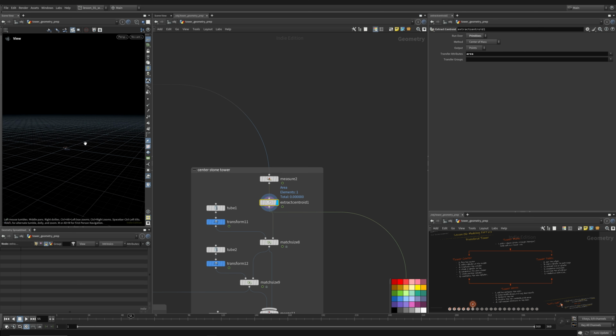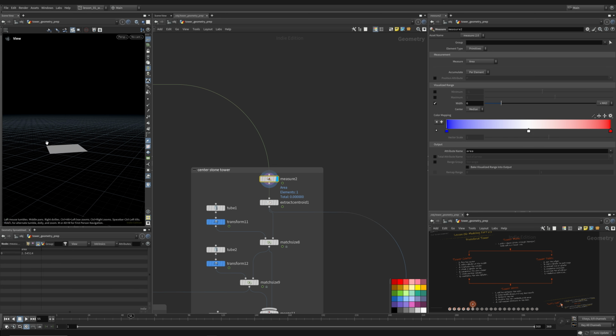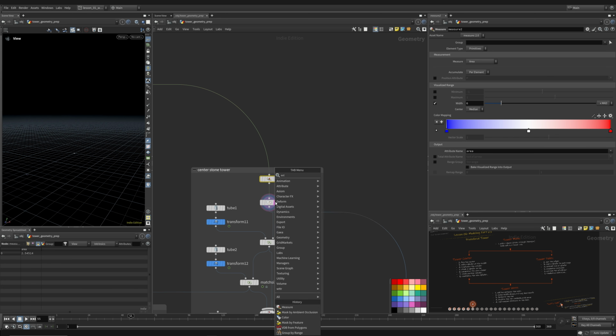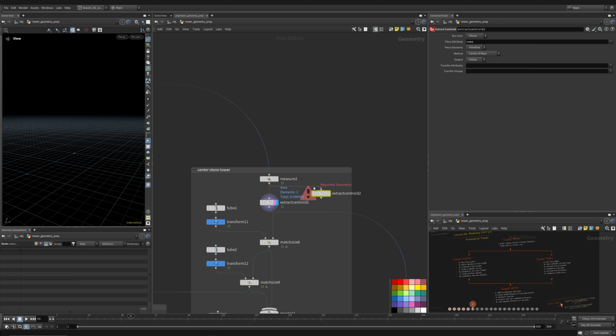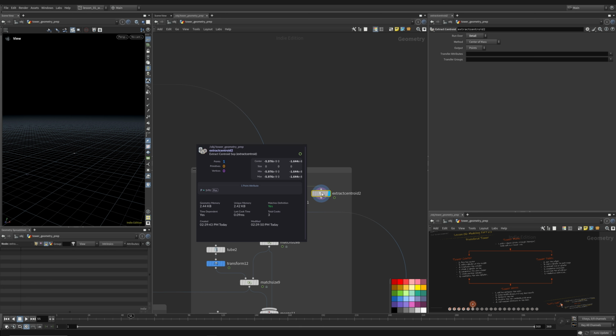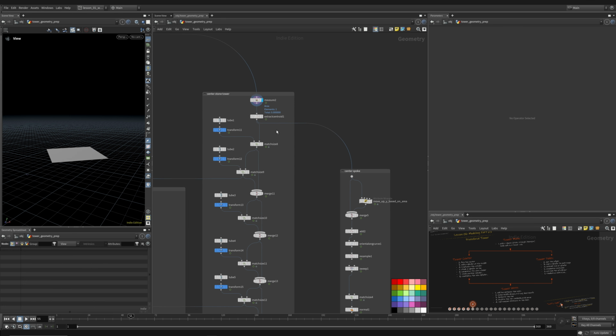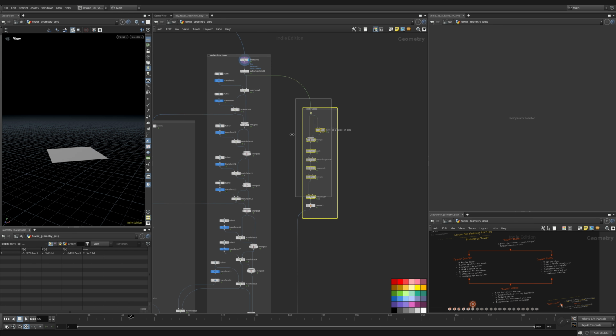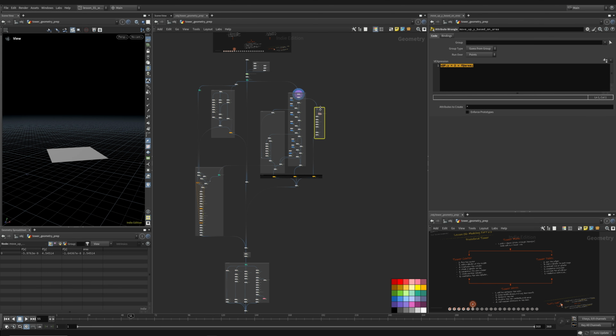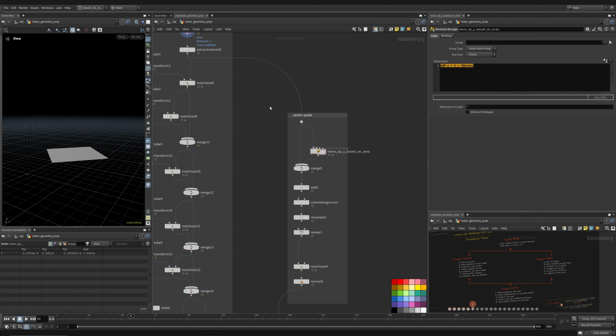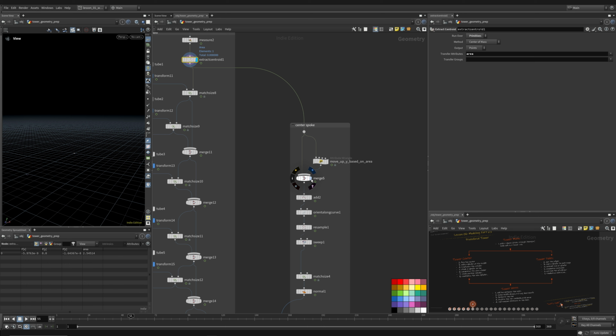We extract the centroid to get the center point of that object, which is done with an extract centroid node set to detail, which takes everything incoming here and gives you 1 point at the center, or the centroid. Firstly, to do the center spoke, we'll do this, and then I'll recolor each of these boxes so we stay a little organized. But we get the centroid.